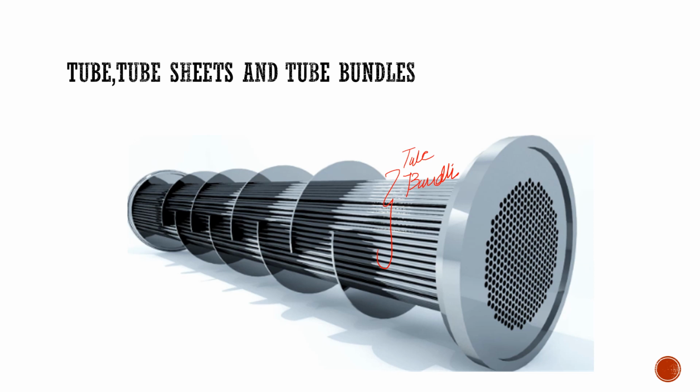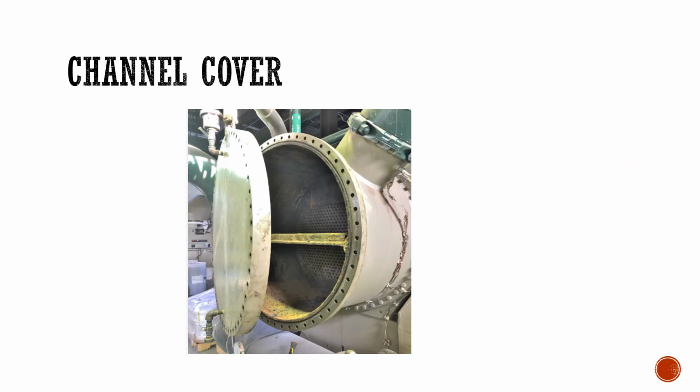The tube sheets are metal plates that support and hold tubes in place. It acts as a seal end and prevents the mixing and leaking of the tube fluid. The channel cover is the part of the shell where tube sheets are available. So this tube sheet can be removed for maintenance purposes through this channel cover.